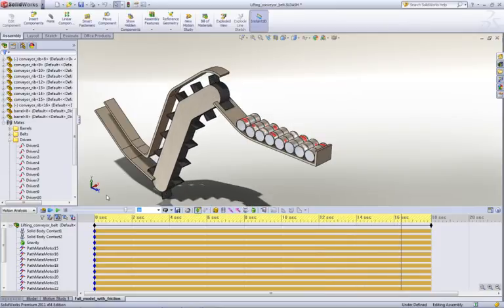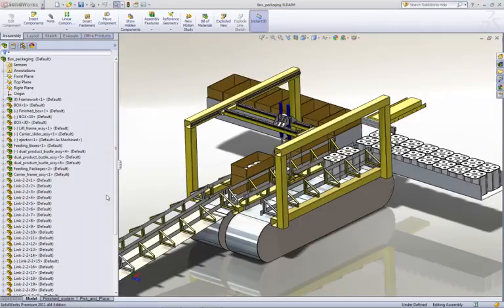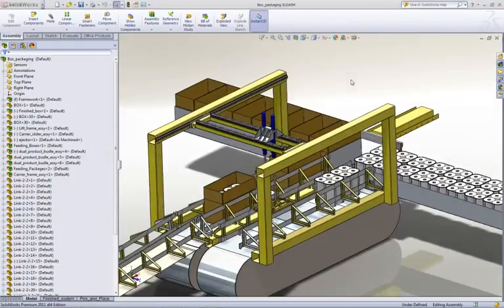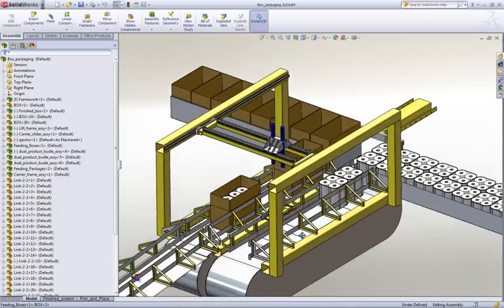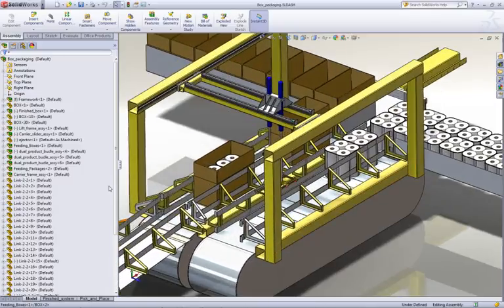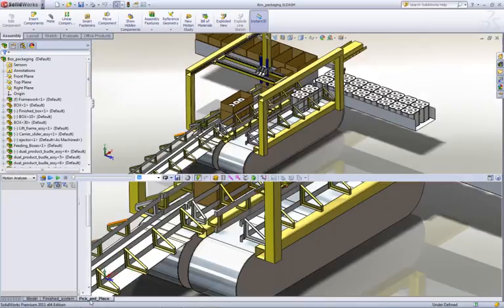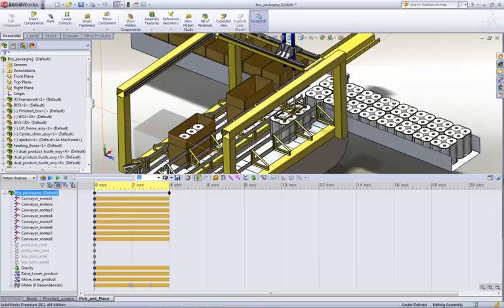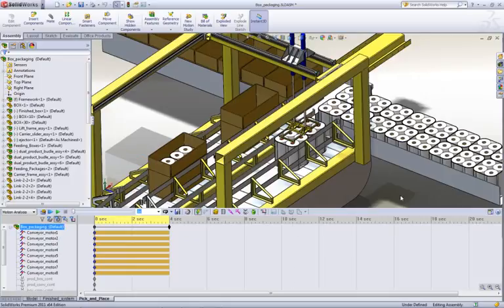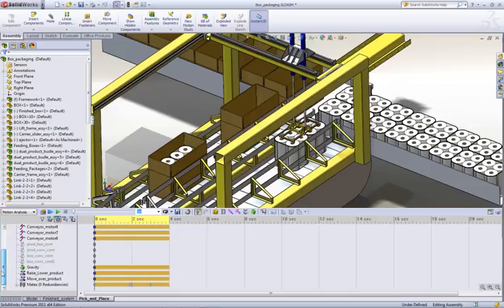Okay, the other area we've spent some time on is focusing on functions. When you have complex equipment, the operation of that equipment can be very difficult to define. So what we've added is the ability to define functions using segments. And what we mean by that is how you would define operation sequences. So you ramp something to go from point A to point B, dwell at a certain position, and then ramp it back down. So for example, when we're picking up this rack of towels,